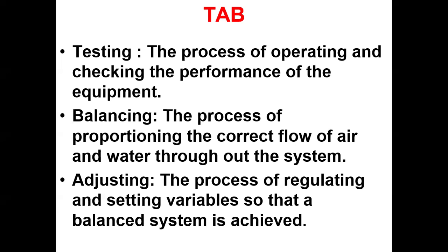Initially, in the concept of fan selection, I explained the working. Once the entire duct system is implemented on site, for example in the Maurya project, according to the heat load analysis, we got a CFM value of around 2,980. For that CFM, we got a tonnage of around 6.9 ton. But on the company side, we don't have any machine for 6.9, so we go with the next available machine, which is 8.5 ton, isn't it? That is around 3,400 CFM. Now we can see a difference of around 400 CFM.